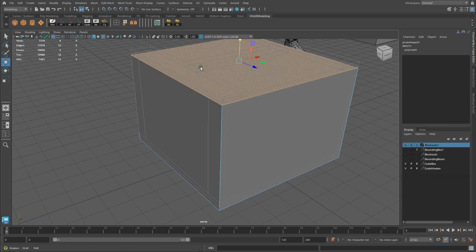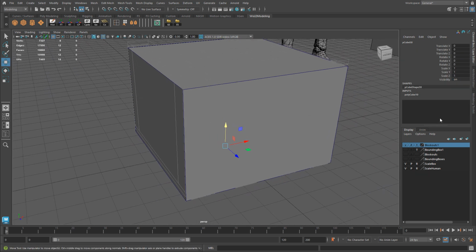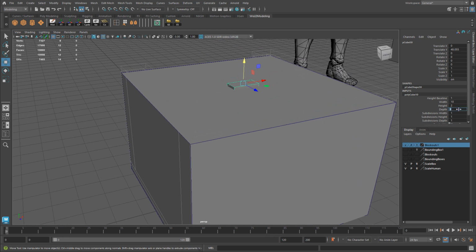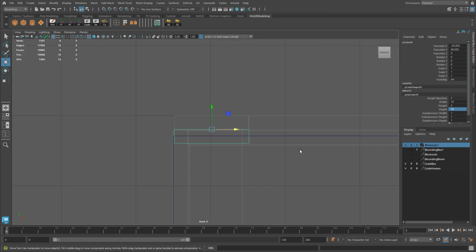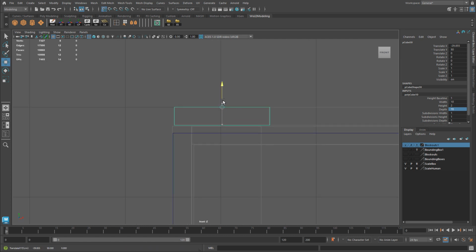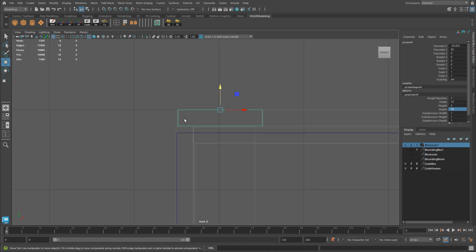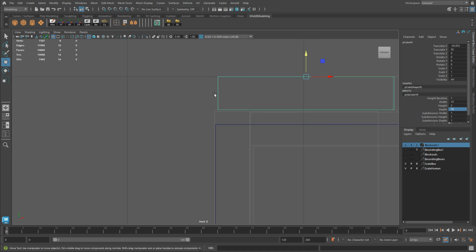And let's create our wooden planks at the top. New cube. This is going to be width at 10, height at 2, and depth at 5. Starting point, and then let's do this one at 1. Let's raise this one higher. Let's see, depth 70. Yep, 70 for depth. And let's just move it over here. And let's go to front view or side view. I'm going to snap this to the very top to the grid, because within our bounded box, that's where we're going to keep it. And I want to make sure that this is close enough to the side.